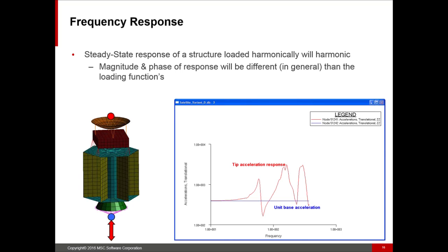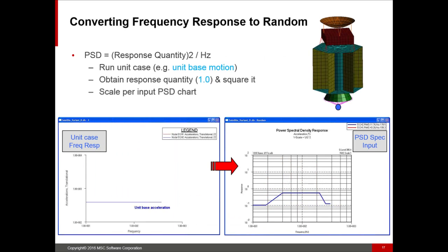It's usually up to about 2,000 hertz or so, depending on what you're working on. Very, very big, very, very small, of course, you could see some differences in what range you need to take a look at. Okay, so this is the frequency response part of it, and what we're usually getting, again, is what the output is at certain points, and what the, if you will, magnification factor is there.